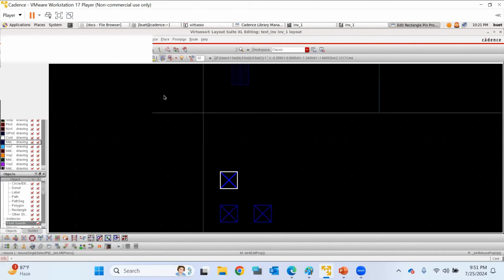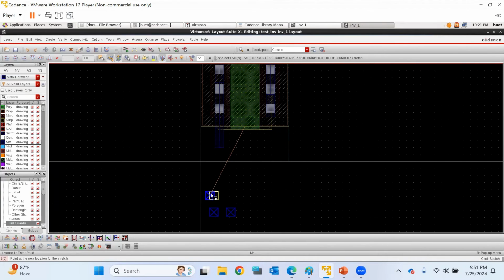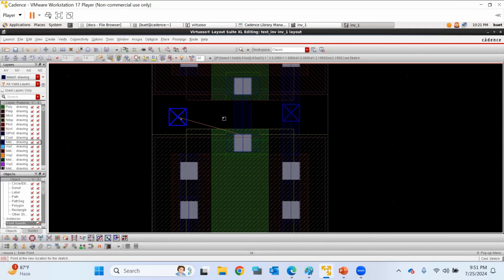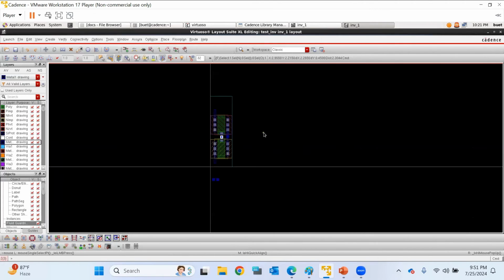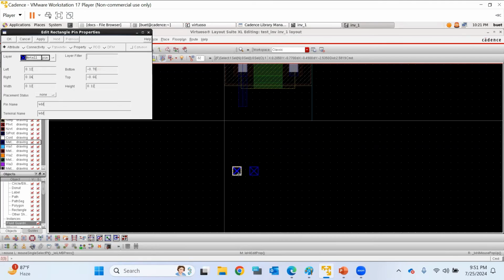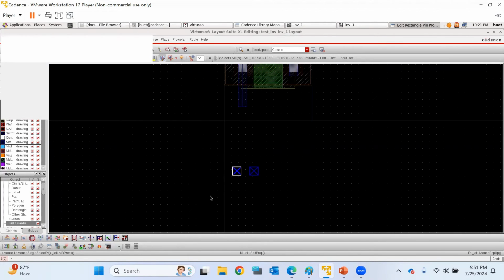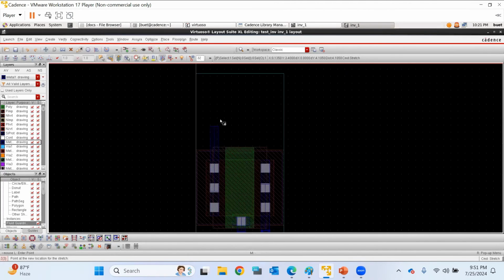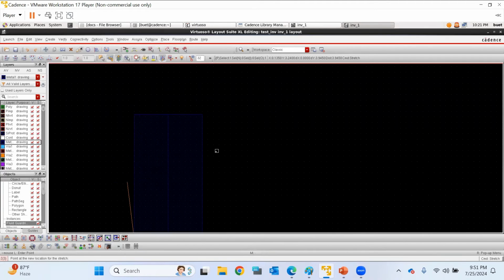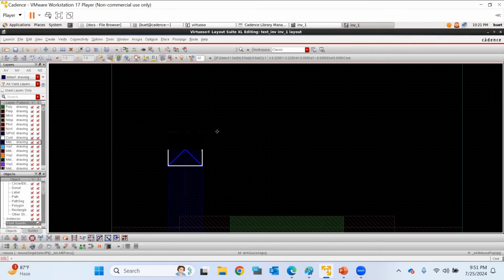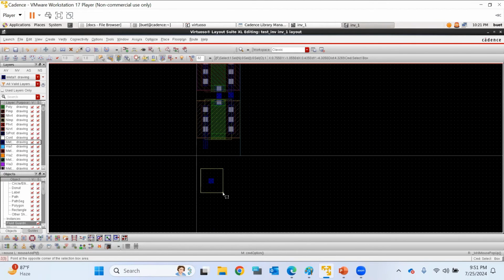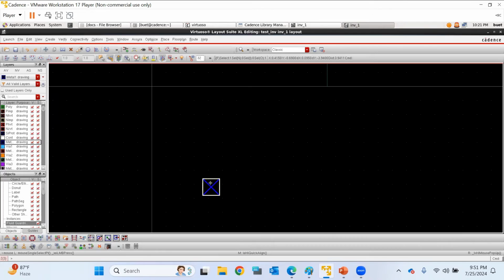This is the input pin. So we take this input pin. See, it is highlighting that orange marker also. Okay. So you put it align here. Aligned. Now this is a VDD connection. We align it with this one also. And this is the VSS one.